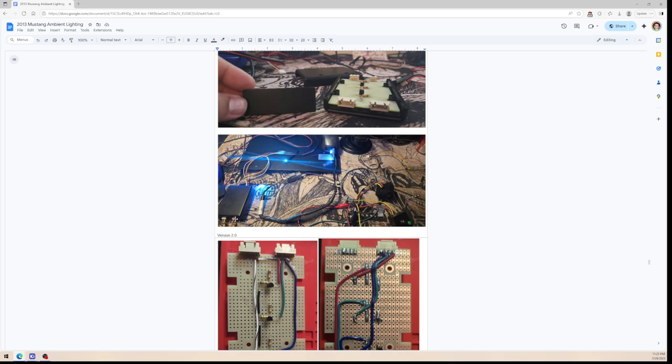Okay, I have my 2-pin port, which is my power and ground, connected to a 12-volt source that I plug into the wall, again for testing purposes. And then if you look here, I have 2 LEDs tested in parallel. One LED is right here, and one LED is right here. And you can see that all 3 of these are showing the same color, because at this time I only had the pulse wave modulator for the blue turned on.